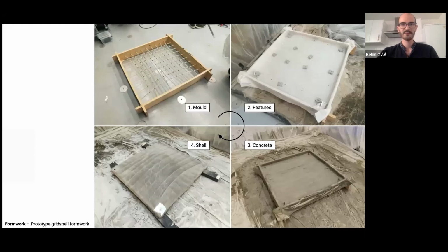This is still in fabrication, but I can show you the prototype that we did in February, on a different type of mold. Here we don't have these vertical pins as before. You can see here the mold with these flexible rods made of GFRP that you can bend and put into shape to get a curved structure. Then the second step was to add different features.